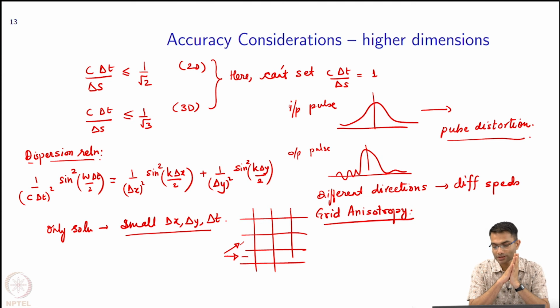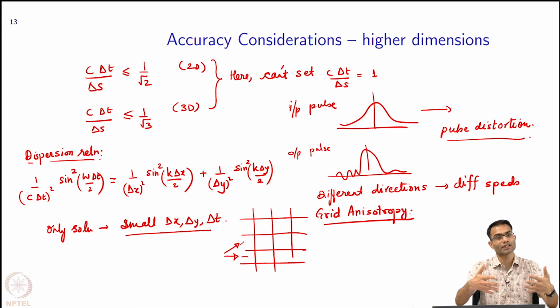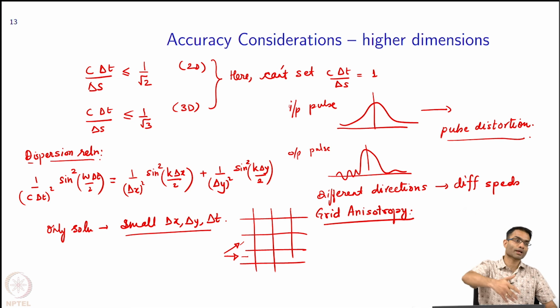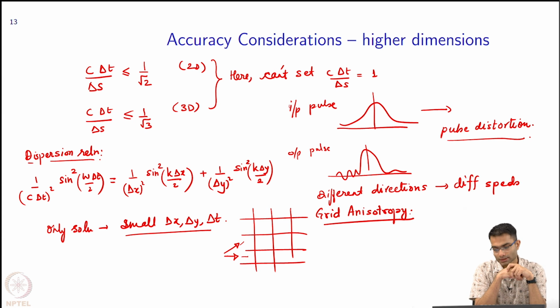So, integral equations. It's tempting to look at integral equations and say none of these problems were there, but integral equations we formulated at a single frequency. So in the integral equation, I'd have to do a Fourier transform to look at pulse distortion. Yes, it's a good point. Integral equations are therefore much more accurate ways of solving computational EM problems. FDTD is like your brute force guy. He gets you the answer after a lot of effort and is still not so good.